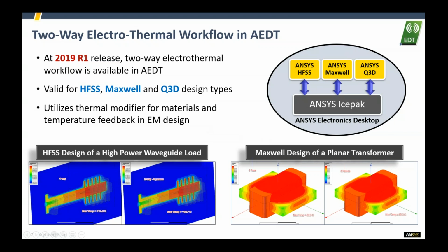Now all these three products are in AEDT already. With this, and with IcePack being moved into AEDT at the same time, a two-way electrothermal workflow is now available for these three with IcePack. The fundamental idea is that they will utilize a thermal modifier for materials and temperature feedback in EM designs.